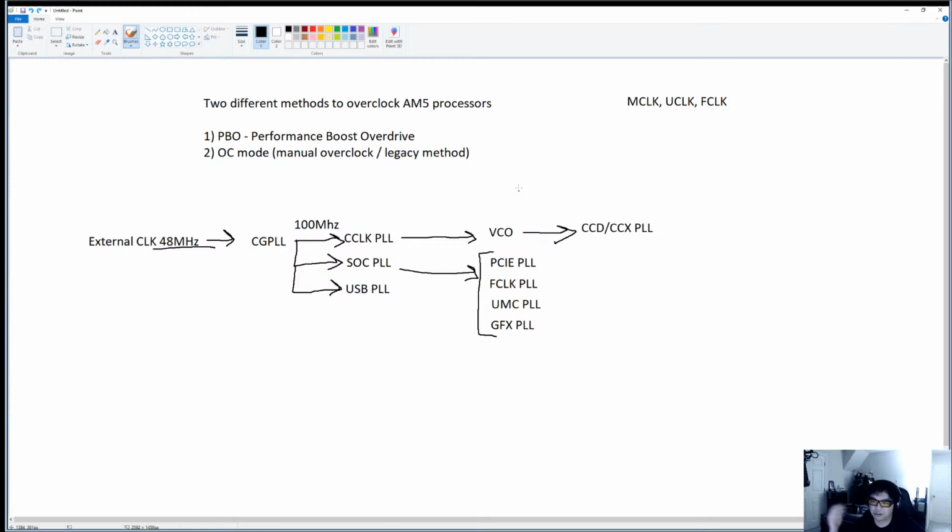It's just a first generation thing versus a second generation thing. Intel was first to the game with DDR5. Granted, when they launched Alder Lake with the DDR5 motherboards last year, those motherboards were very expensive, and the DDR itself was very, very expensive. So AMD is running into the same wall of issues that Intel had to deal with last year as early adopters of DDR5. So, unfortunately, the IMC is kind of picky. I don't want to say flaky. It's not flaky. It's just that the quality of the IMC for a first generation product leaves a bit to be desired when it comes to high-speed memory.